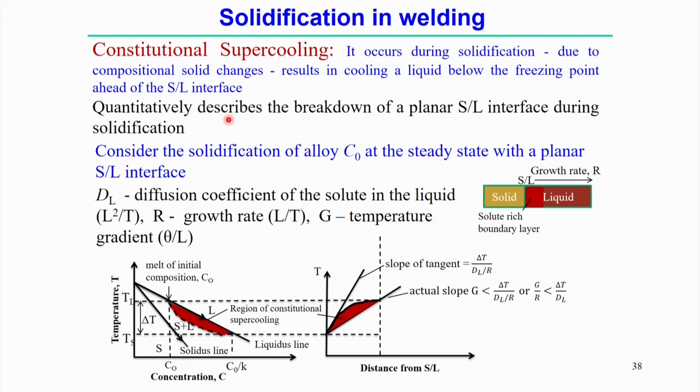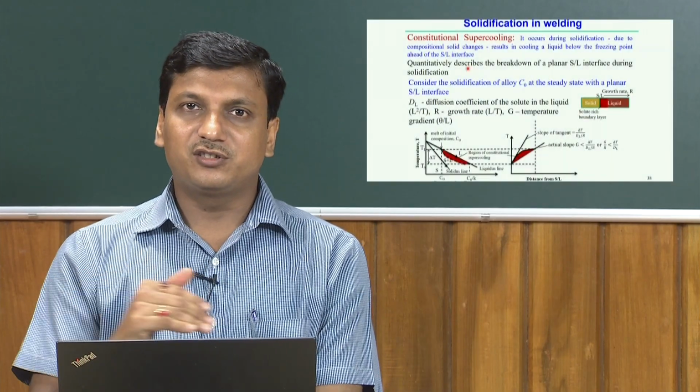Of course, it pertains to some conditions, that is, before the start of the phase change, the nucleation mechanism involved in the solidification process is governed by the amount of supercooling temperature, that means the temperature below the solid to liquid transition temperature.